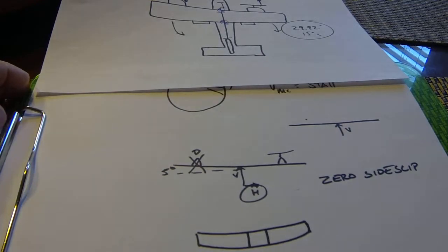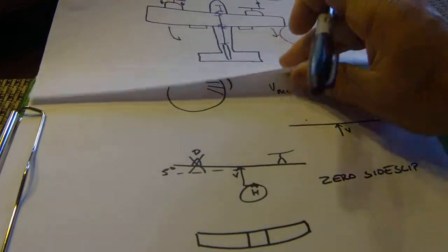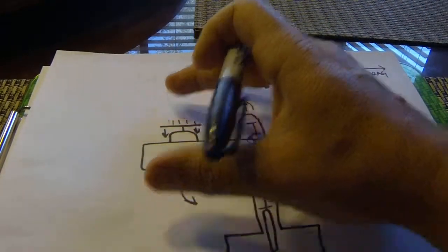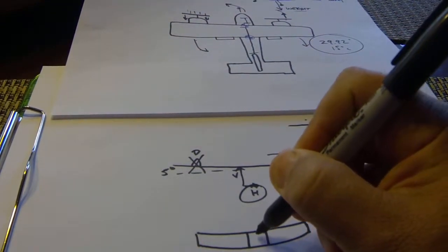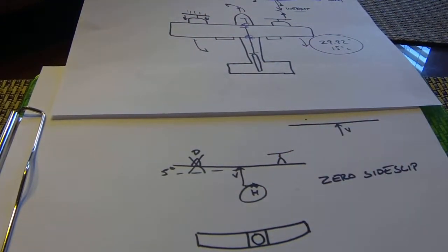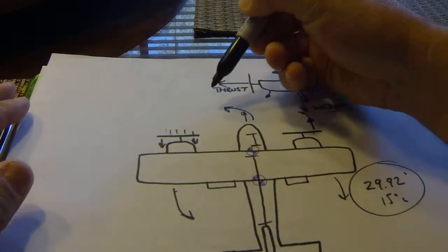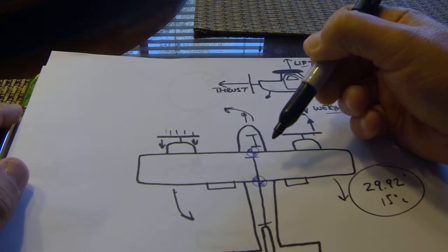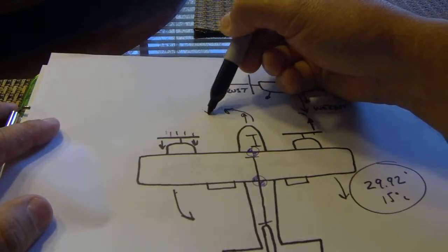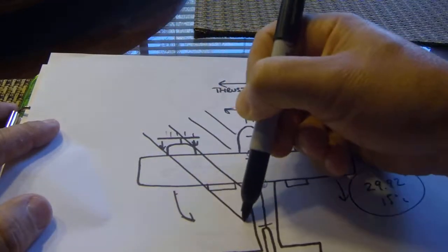That's our inclinometer and our turn and bank indicator. With one engine operative, all right, with our critical engine out, one engine operative, if we center the ball right here, as we are normally accustomed to doing, we are going to fly with a side slip towards the inoperative engine. Okay, so the relative wind is coming like this, hitting the aircraft at its side.